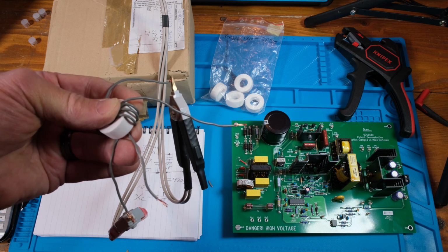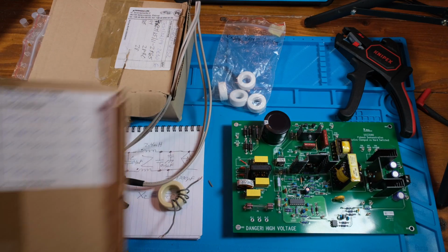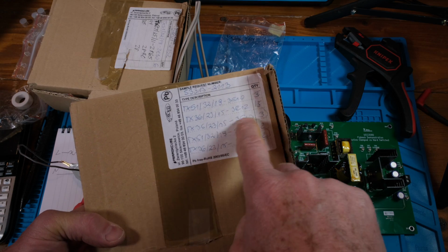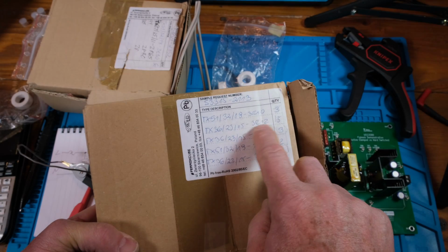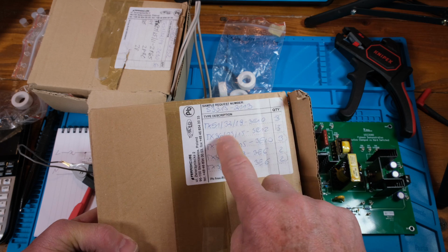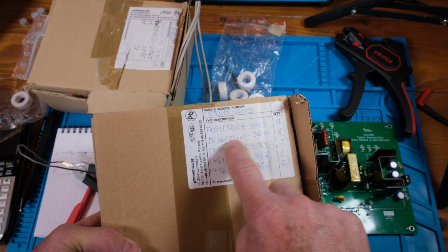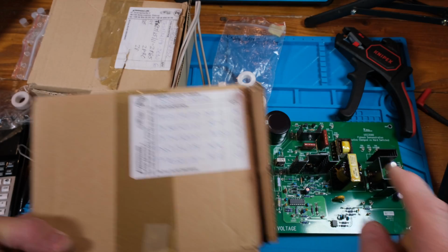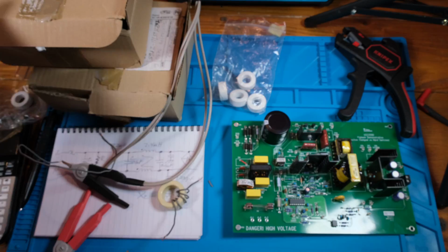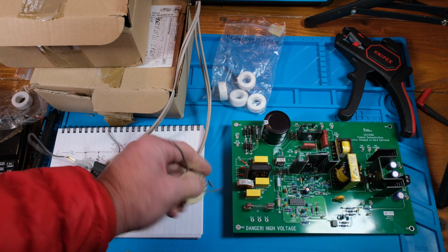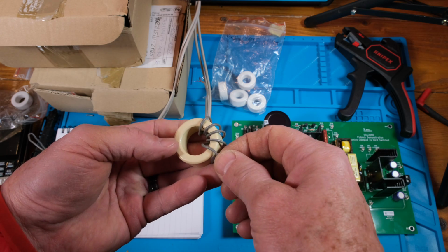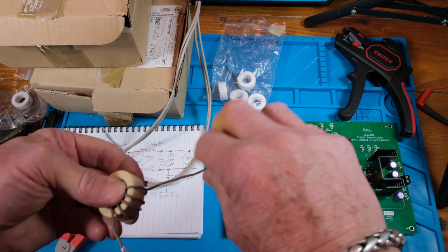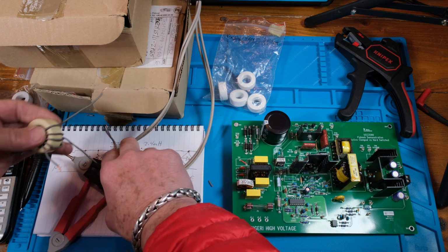And we have about 2 microhenries. All right, guys, that wasn't as much inductance as I was hoping for. So I recognize the 3E12, and that's a 36 millimeter core. And I recognize that 12 as being the high permeability. This other one's not quite as high. So I went ahead and wrapped the, well, let me see. I actually have 5 turns on this one, but here, let's measure this.